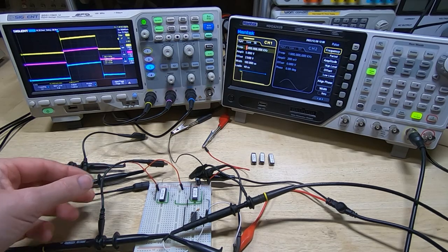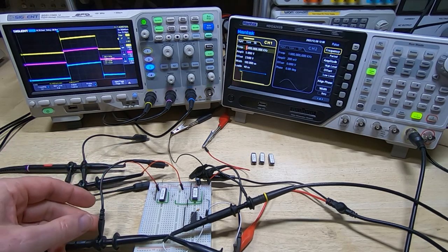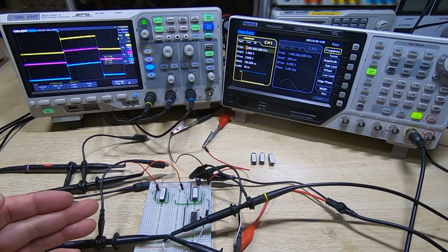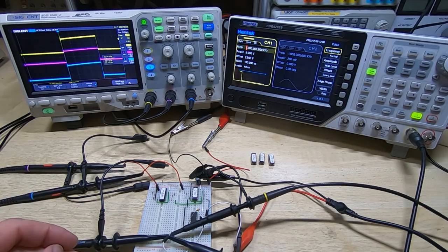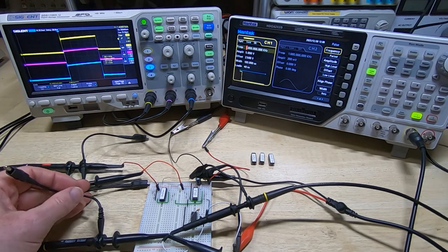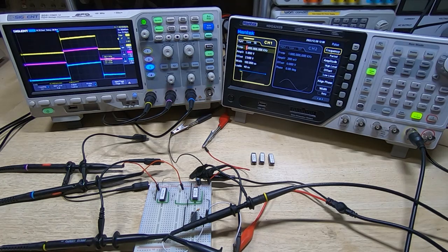In fact, I normally remove the ground leads on the probes completely, just to make it a bit easier to test. I do sometimes attach them and find a local ground on the board if I'm looking for a very specific signal or want to examine a signal in more detail, but as you can see, you don't need these connected, and it will have no real bearing on the testing that we are carrying out here.